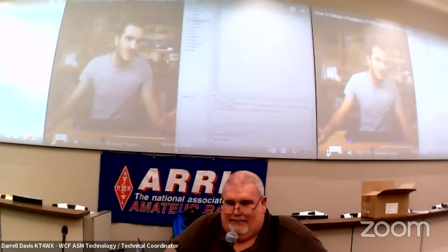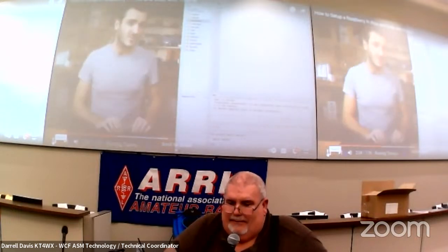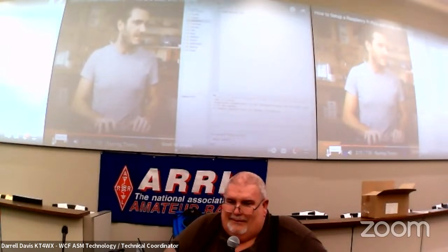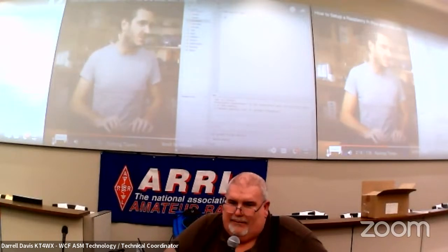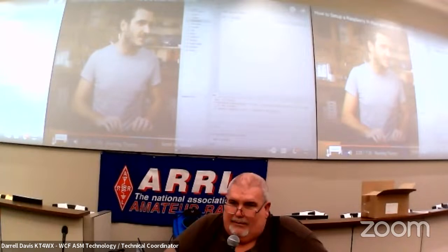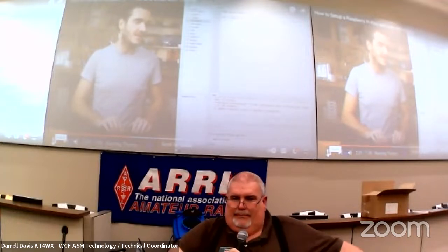The script. This here is our empty untitled script. First thing is to import some packages. This will give us the ability to control the pins on the Pico. I'll assign LED to pin 25. That's the pin on the microcontroller that the LED is connected to. We call that the output.